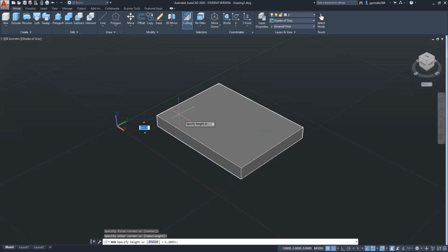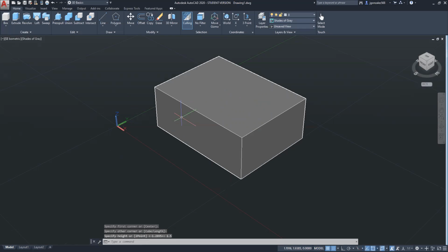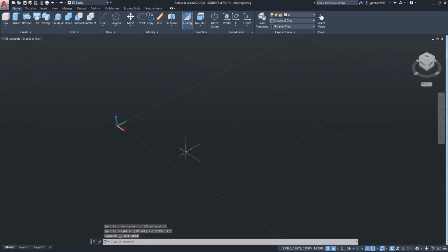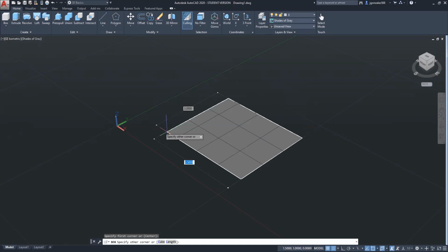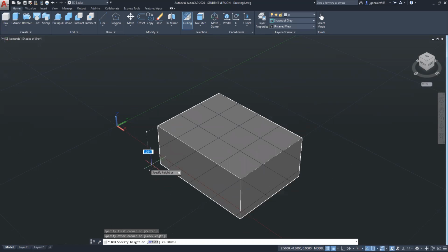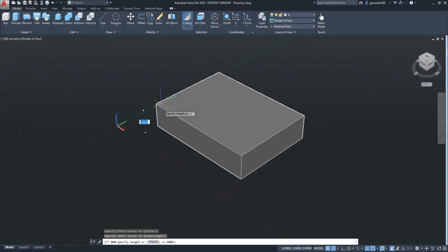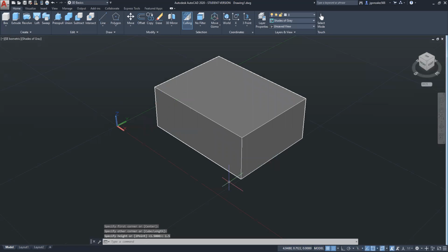So once you create the base, I want you to do a height of 1.5 for this box here. Let me try that again so you can see what's going on. So 5-4 all the way to 1-1. Notice how it can go up or downward. So make sure it's on the way up before you type in the height, because if it's on the way down, it's going to go downward. You see what I mean? So now it's upward because that's how it was starting to adjust.